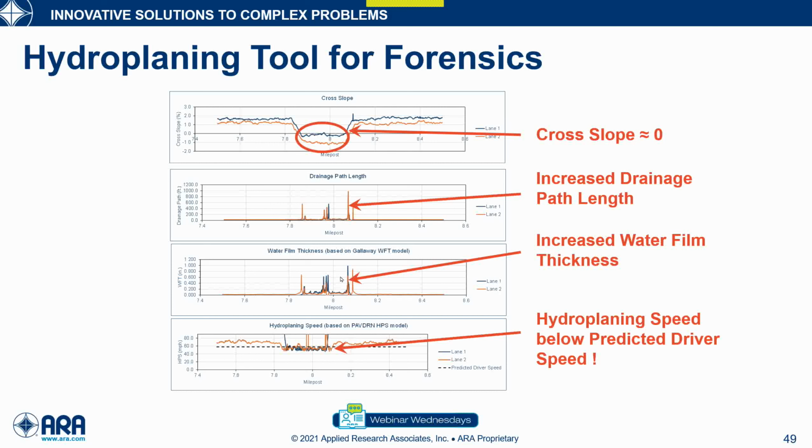That was a very good question, and I had the question when I was starting to get into hydroplaning as well, and I asked one of the drainage engineers from Turnpike if he could provide me some insights on that. And you can see here there is a transition zone, and of course you're going to have the long drainage path, but this is not a transition zone. So when you have something like this, you should have controlled the crosslope differently. And about how long it should be, that depends on several factors, the total length of the roadway and the geometry of the roadway. So it's not as easy as saying it shouldn't be longer than a tenth of a mile, but it will depend on the geometry conditions of the particular roadway.